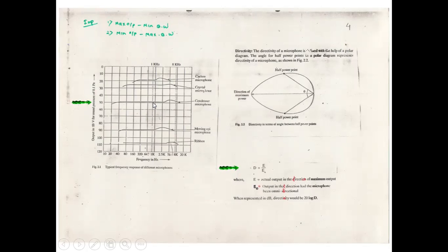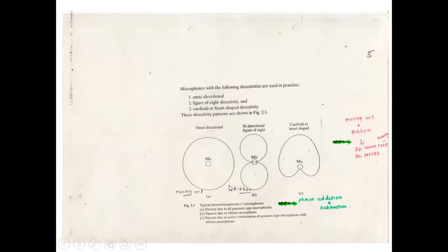That's why for calibrating sound equipment and sound related meters, this condenser microphone is used. And for the PSTN network, you want the maximum output. For speech, the frequency response is not that important. Whenever you are talking or using this PSTN network, normally this carbon type of microphone is used for that purpose.